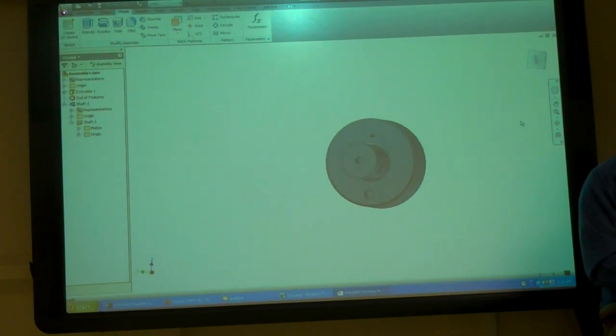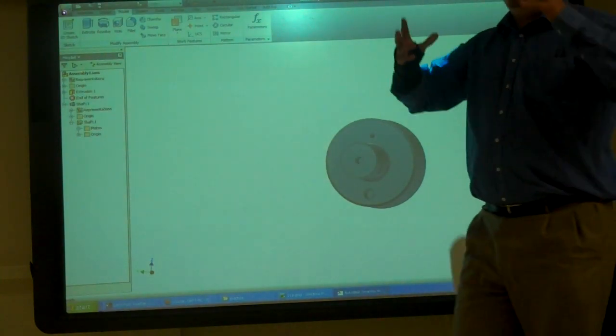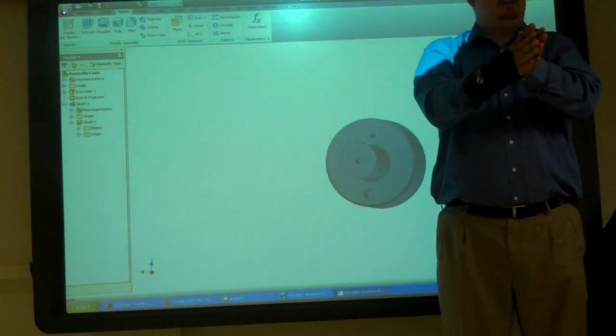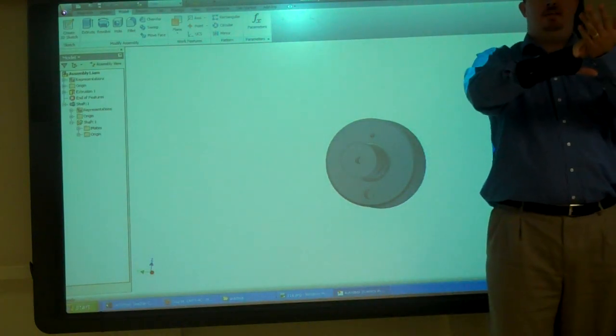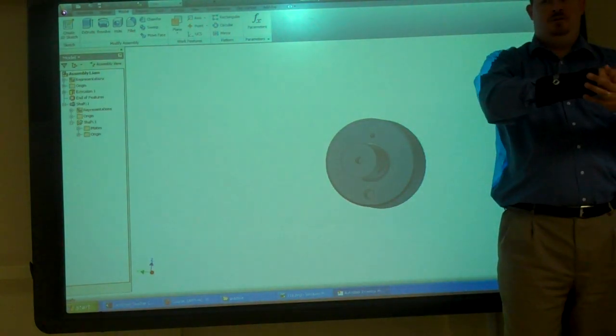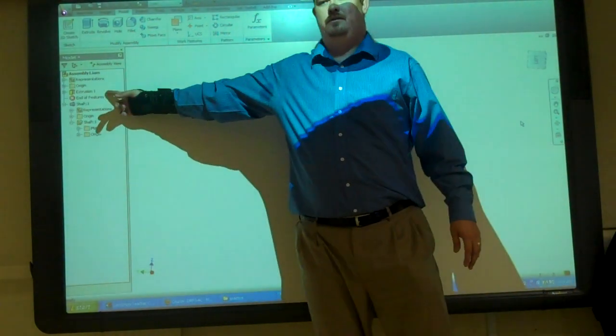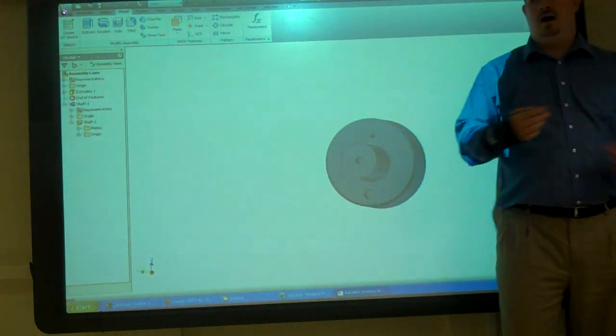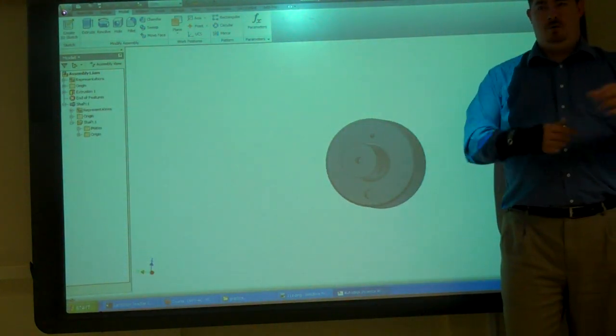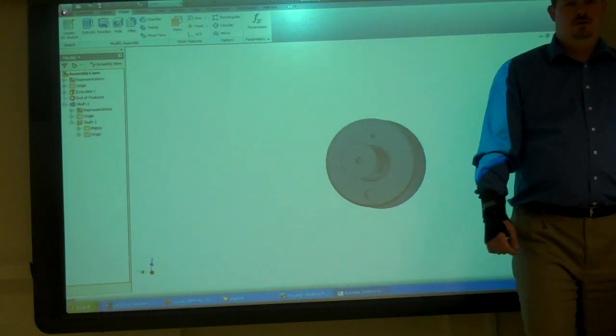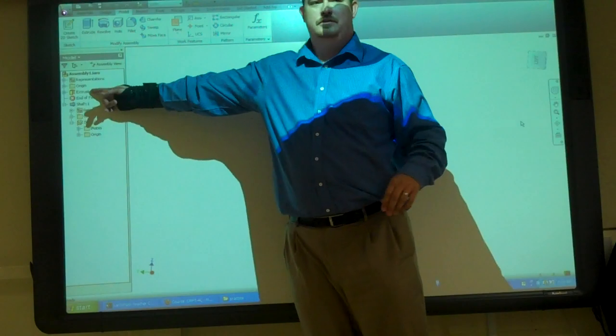Modification. Kind of. You're on the right track. You can do it there so that after you're done making the part and you're putting it together into the assembly, you want to do some extra things, like you put the two parts together and then you drill a hole between them to make sure that hole lines up. That'd be one reason why you'd put it there in the assembly. So that it's not on the part drawings, the machinist doesn't see that hole, but when they're at the assembly, then they do see it.